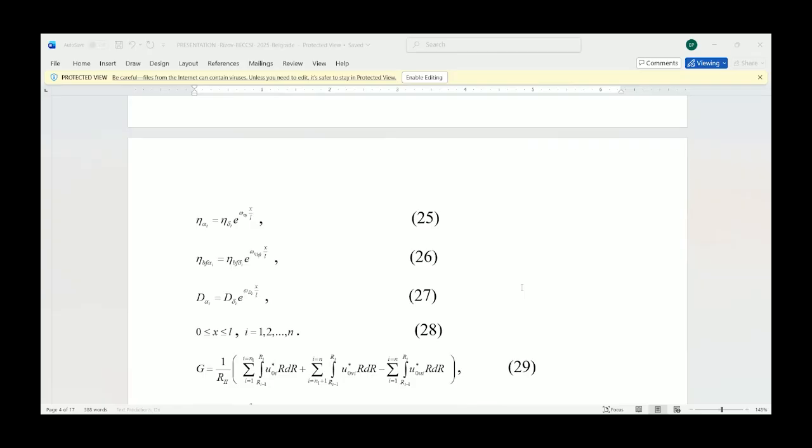As already stated, there is a delamination crack between the layers of the moving rod. The crack is a circular cylindrical surface with radius R2 and is located in part B1, B2 of the rod. The crack front is in section B2 of the rod. The delamination crack length is A. The strain energy release rate in the rod is found by using equation number 29.